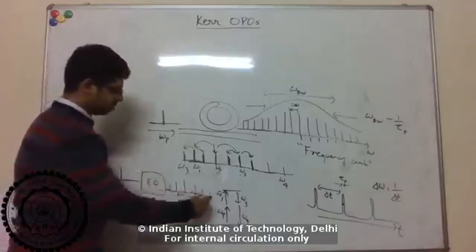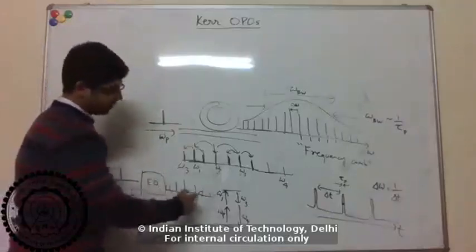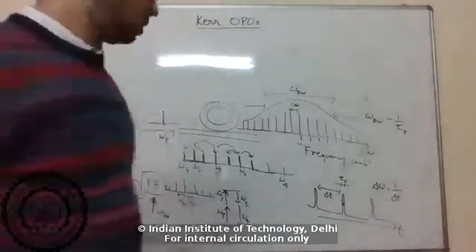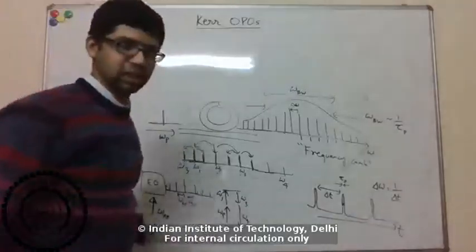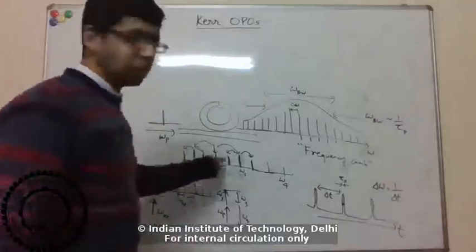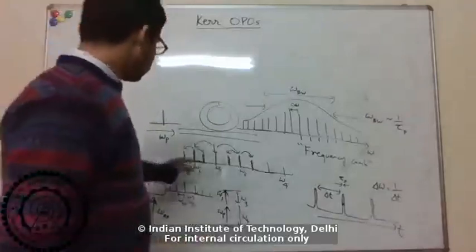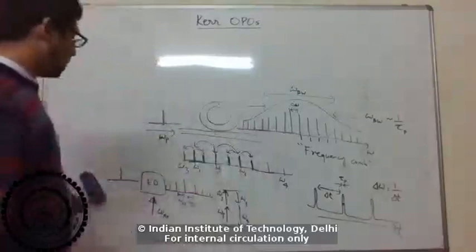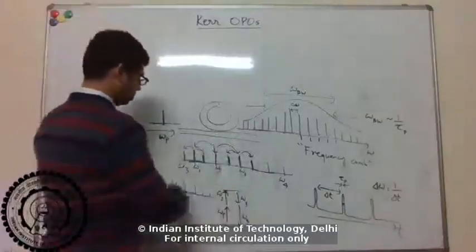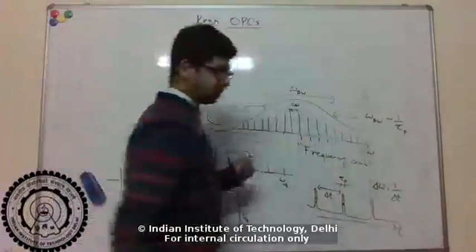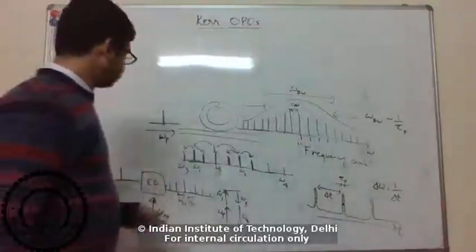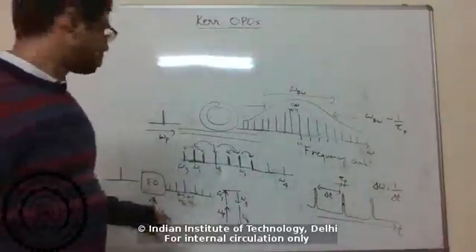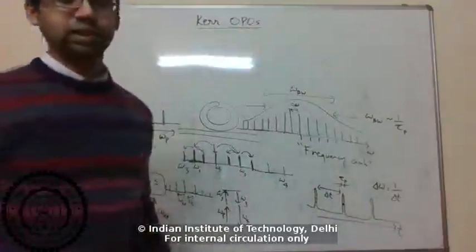So typically you can get maybe tens of lines here when you drive the modulator to maximum with all kinds of amplifiers here and before. You could even cascade modulators, right? So that's also a field of research on its own, electro-optic based frequency combs. Okay, but the limitations are, first of all, how much bandwidth you can get, like how many lines can you get? Typically limited to maybe tens of lines. So maximum, let's say you can do maybe 50 lines, 100 if you stretch, if you cascade many modulators, etc.